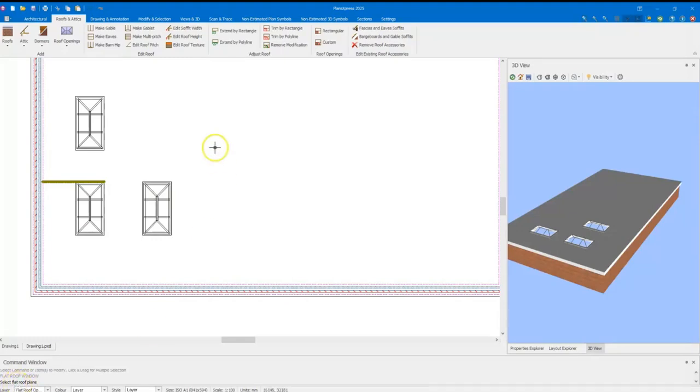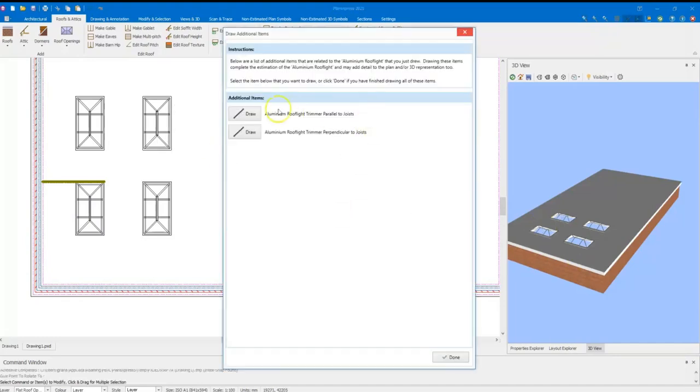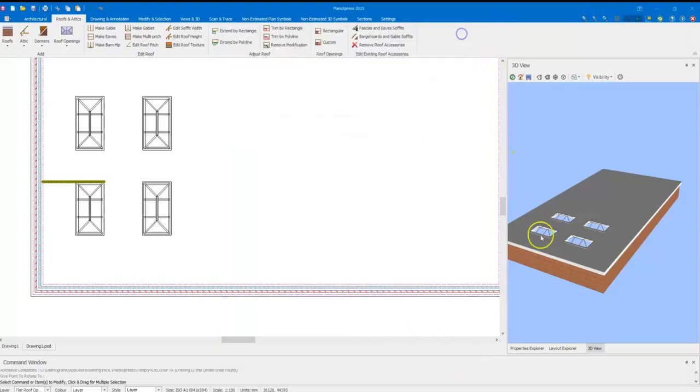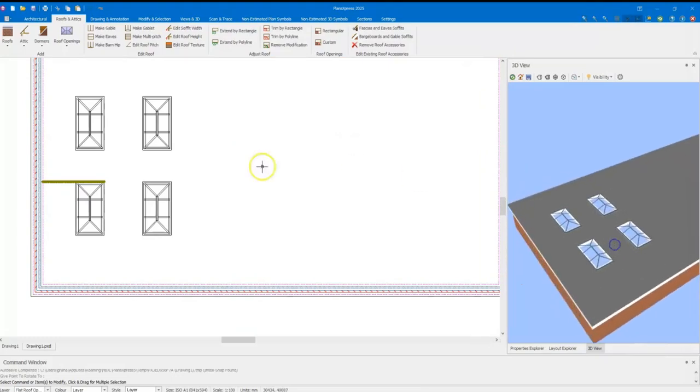And so we're back to the draw roof lantern command, which is to select the flat roof. So I'll just come and click there. I will come here on the snap point, press X to lock that axis. I'm going to come along here, press Y to lock the axis again, and click, hold Shift. This time it will lock vertically. Press click, and again we have this, which will show you either done or close up. We now have 4 roof lantern copies.